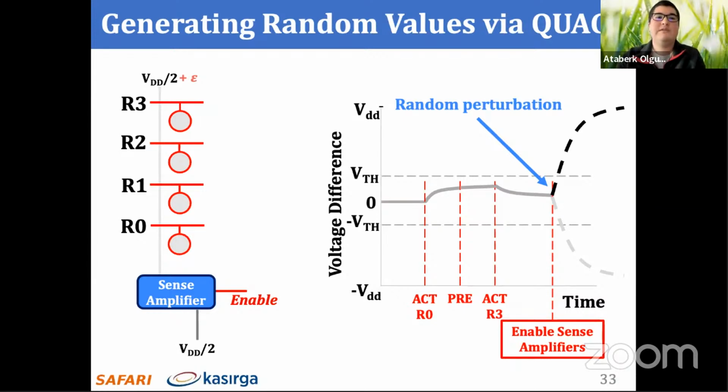So if we could enable the sense amplifier without sending an activate command when the bit line is pre-charged, we could potentially generate random values on all bit lines or on all sense amplifiers in a row, and that will bring us to 64,000 random values per activation instead of what we get, which is around 2,000 on average in QUAC-TRNG bits in the full segment.